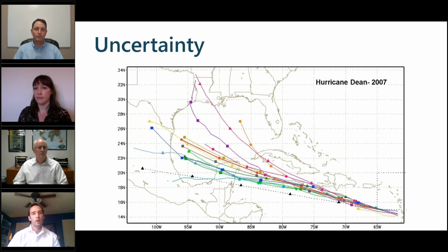Through the process of inverse modeling, whereby the parameter values are estimated from a limited amount of data, it produces non-unique solutions. So the scenario outputs can be viewed as more probabilistic than deterministic, and they have a range of possible solutions, even if you're only running one model and you only have one answer. Uncertainty can be, as Wade mentioned, a bit of a dirty word regarding groundwater models, especially those that are used for regulatory or water management purposes.